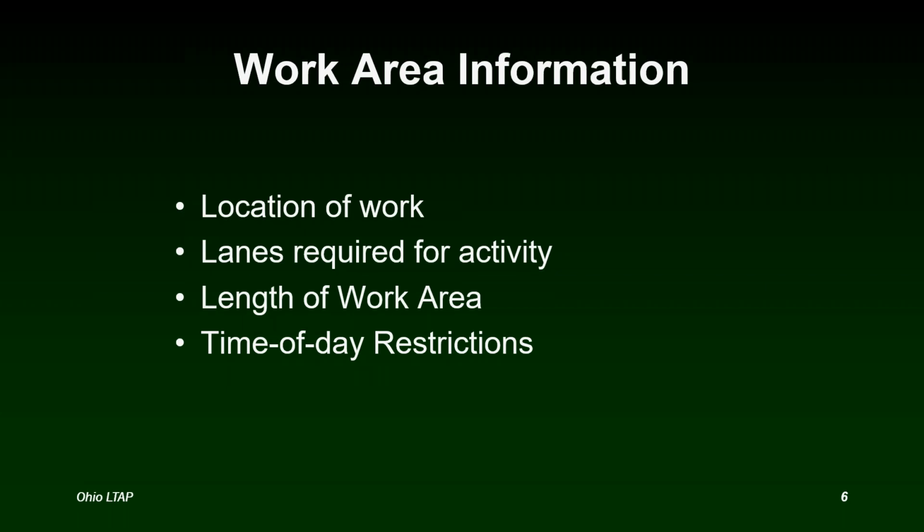And that's good because that's going to be utilizing a typical application as the basis of your work zone design that day. So it's very important that before you leave the garage to go out there and work on the road that day, that you have a plan in mind, maybe a hand drawing, or we like to stress a tailgate safety talk before the workers go out and work on the road that day. And part of that tailgate safety talk should be all about how you're going to set up your work zone that day. And so how you set up your work zone is based on a lot of different things.